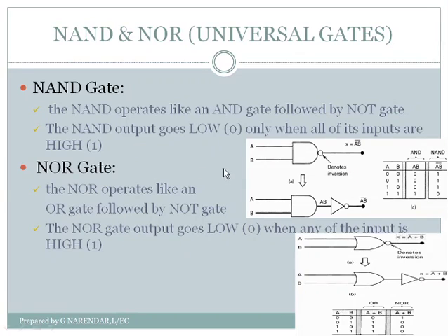And here we have seen that the NOR operation performed by the NOR gate circuit is equivalent to performing OR operation first, followed by performing the NOT operation on the result. And here we have shown the logic symbol where we have shown that it is equivalent to OR gate followed by NOT gate, and here we have shown the input and output relation for the NOR gate.